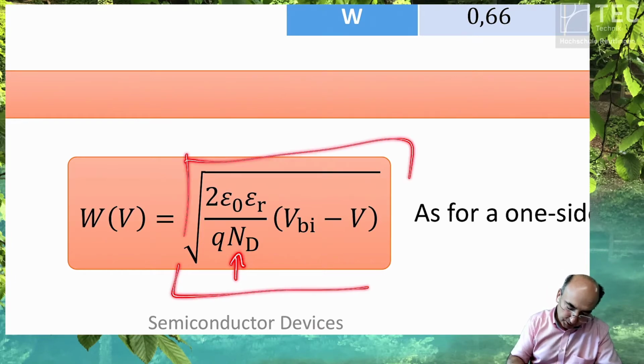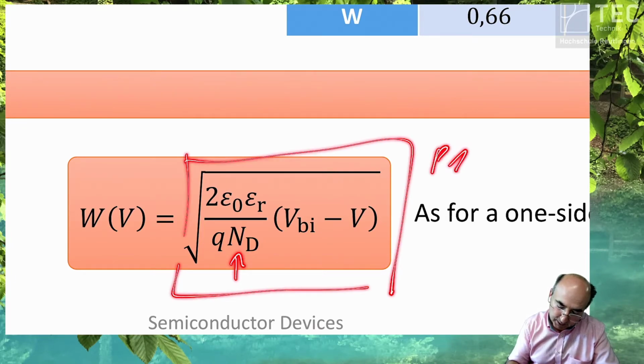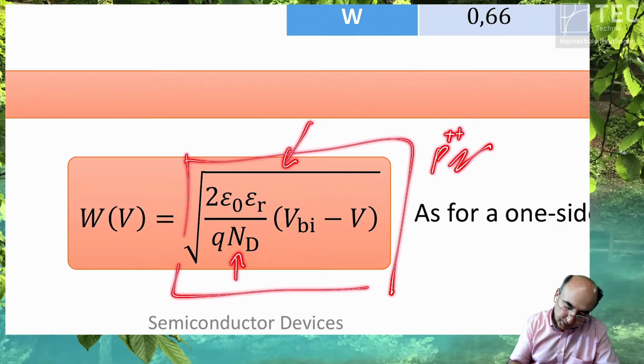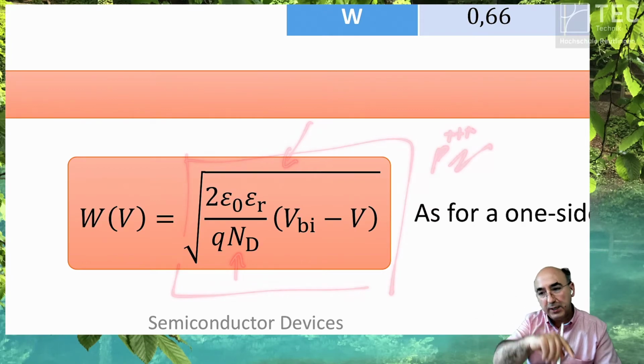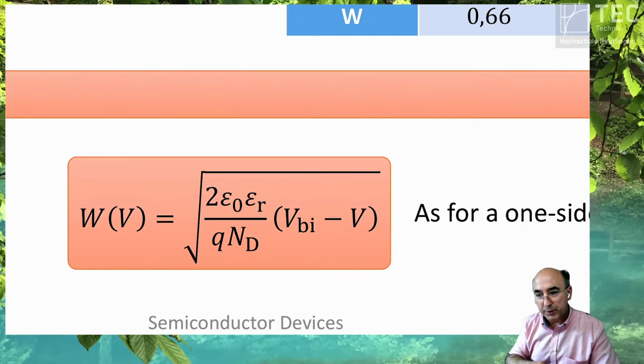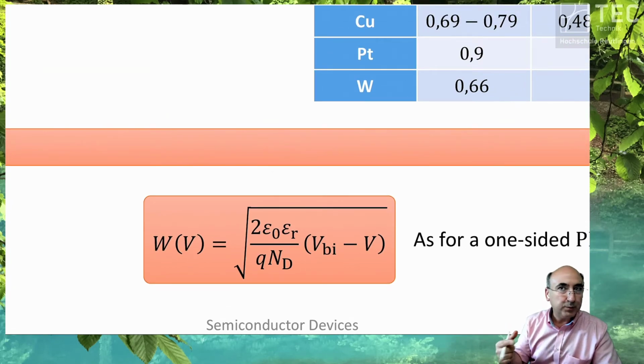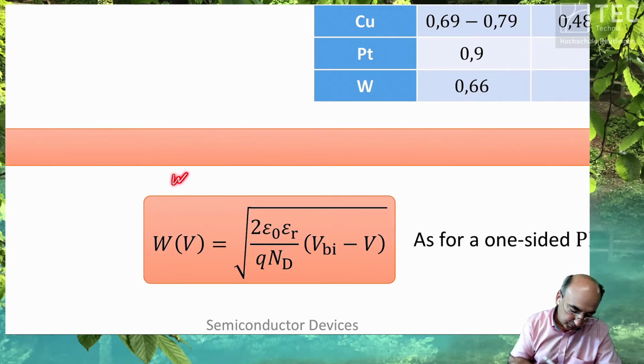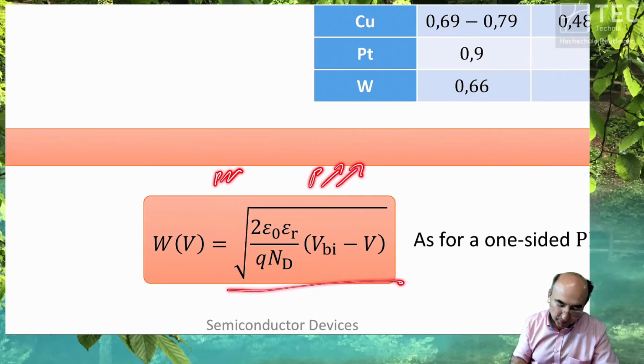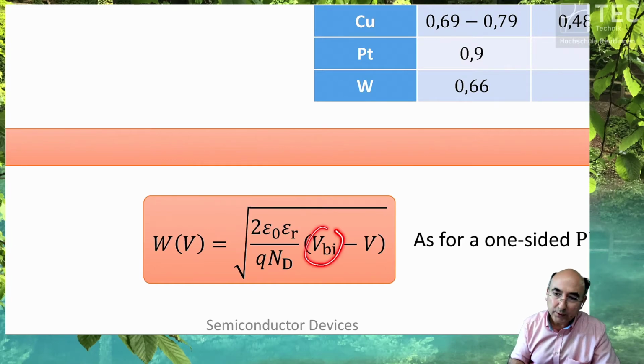If you take this equation and compare it with the p-n junction, you get this equation if you increase the p doping level to very high values. Just take it in your going through these materials yourself after the lectures. Take the equation of the space charge region for the p-n diode and let the p doping increase. Then you get this equation for sure. The built-in voltage, yes.